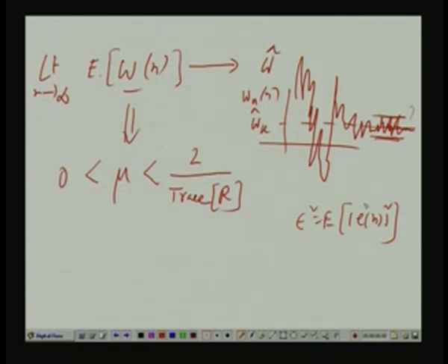But if you do not put the optimal filter, naturally the error is not minimized, so epsilon square is something more, there is some extra term delta. What is epsilon mean square? If you really put the optimal filter weights, find out the E n and find out its variance, that is the minimum possible error variance attainable, which we call epsilon mean square.